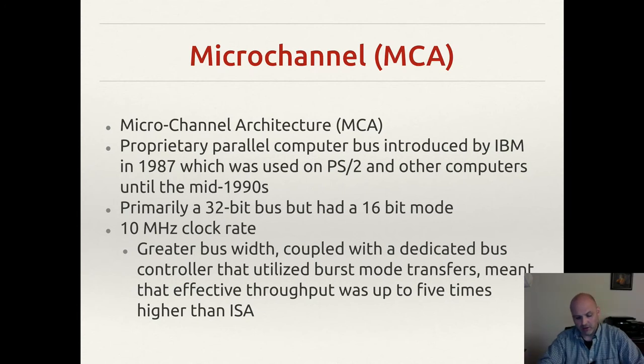So the way that worked is the bus speed on that machine should have been 25 megahertz, and then the processor ran at 4 times the bus speed. So basically they could keep things in sync by doing something once every 4 cycles or something like that. It was very rudimentary by today's standards. The controllers are much more complex today, but that's how it started. This started with a 10 megahertz clock rate, but it was able to go up from there.